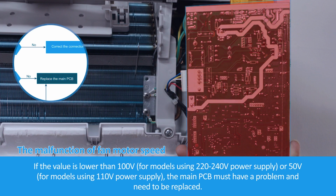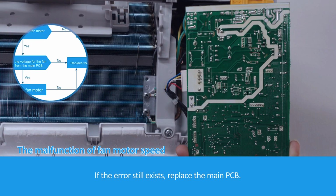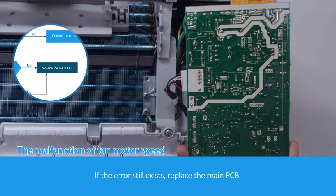If the value is lower than 100 volts for models using 220 to 240 volts power supply, or 50 volts for models using 110 volts power supply, the main PCB must have a problem and needs to be replaced. If the value of the voltage is normal, the fan motor needs to be replaced. If the error still exists, replace the main PCB.